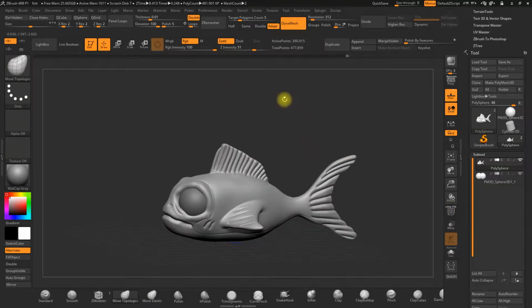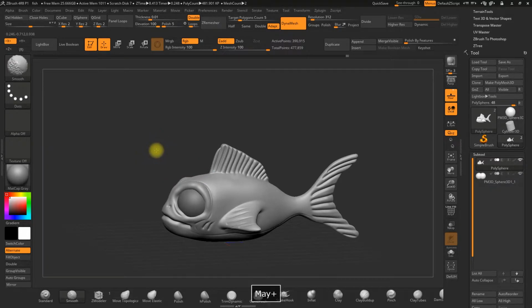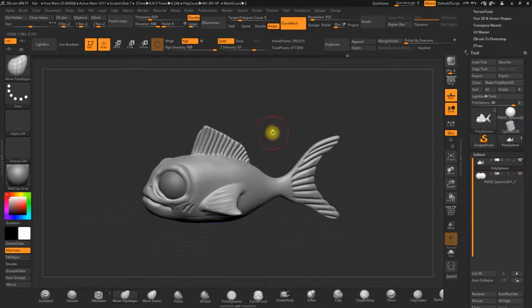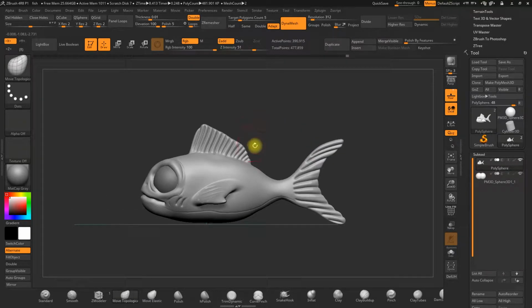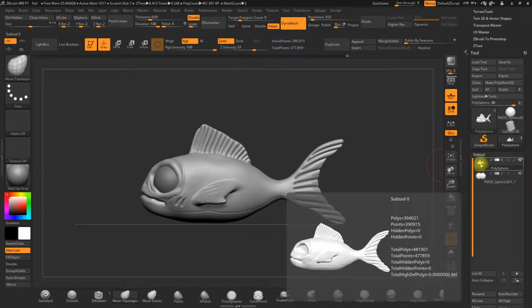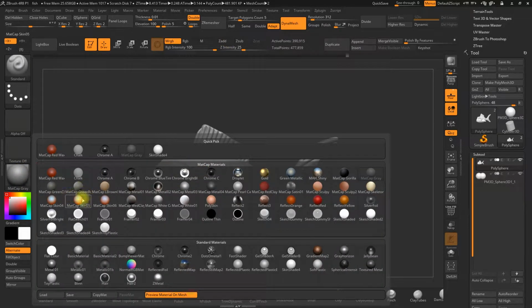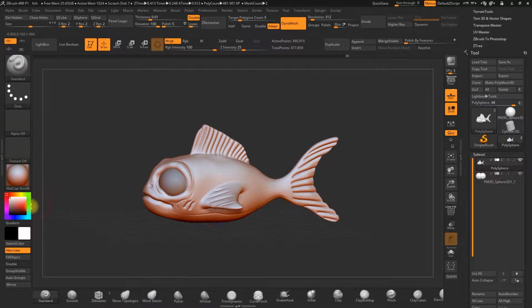Great. As I was saying, the next step would be to apply some color or some kind of alpha. In our case, we will directly apply some color, nothing else. So for this, here we have the eyes, and here we have the fish, okay? We select the standard brush. We check the mRGB box, which enables us to paint both materials and objects. We disable this box here. And now we can choose any default material. And we can paint the model now with a color.